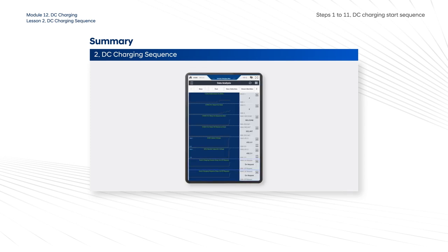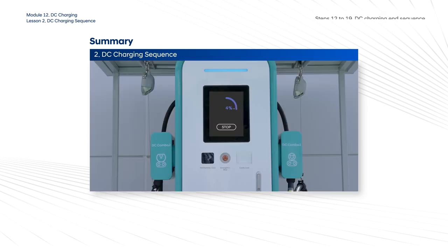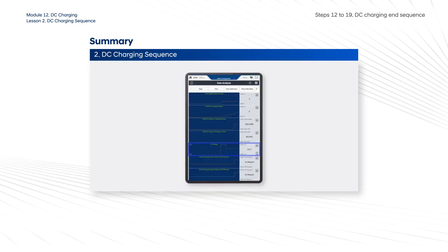After that, the BMS activates the quick charger relay. Then, the EVSE starts power supply. When the charging stop button of the EVSE is pressed, the CP voltage changes to 9 volts, and the quick charger relay is deactivated with welding inspection. The EVSE discharges the internal capacitor, and the multi-inverter discharges the neutral capacitor. The MCU stops PWM control, deactivates the 400-volt relay, and the BMS deactivates the main relay.